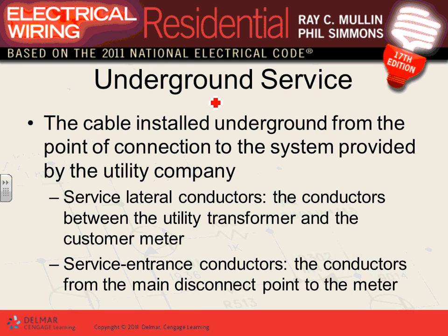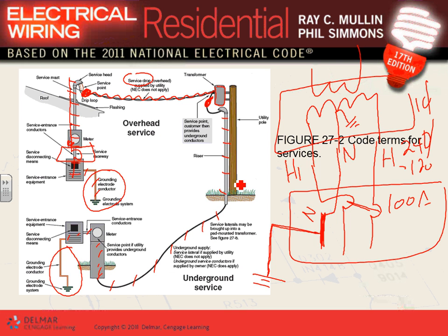Okay, now if you're going underground, cables are installed underground from the point of connection to the system provided by the electrical utilities. When you're going underground, guys, it depends who's going to provide the conductor, and that depends where the service point is. So let's go back into this one. If my service point is right here, then you, Derek, my friend, will be providing all these conductors and the pipe all the way up to this point. If your service point is right at the meter, then the utility will be providing all this cable and conduit.